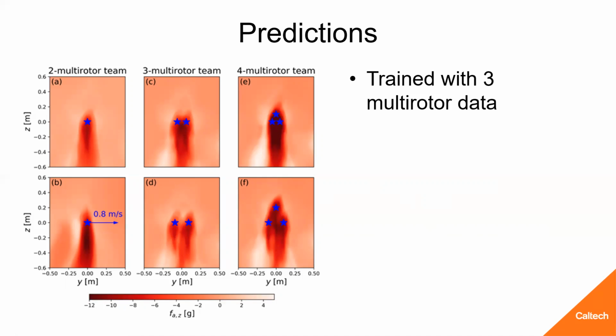Maybe also a question to that. Some areas on the right are actually white, which seems like an upwash instead of a downwash. Is that true, or is it just an approximation error? That's actually super interesting. We tried to figure out with fluids people what's going on. And our current belief is that the neural network actually learned another residual dynamics that we didn't model, which is the modal delays.